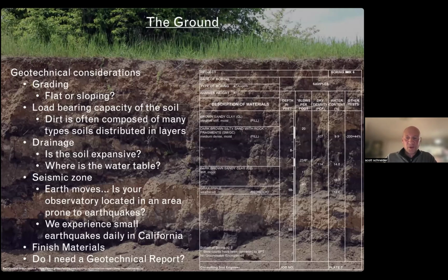As you can see in this boring sample here, this particular location has a lot of silt and clay, and then it has bedrock below. Luckily the bedrock in this case was not too deep, so these particular foundations were able to bear on the bedrock to support the structure.